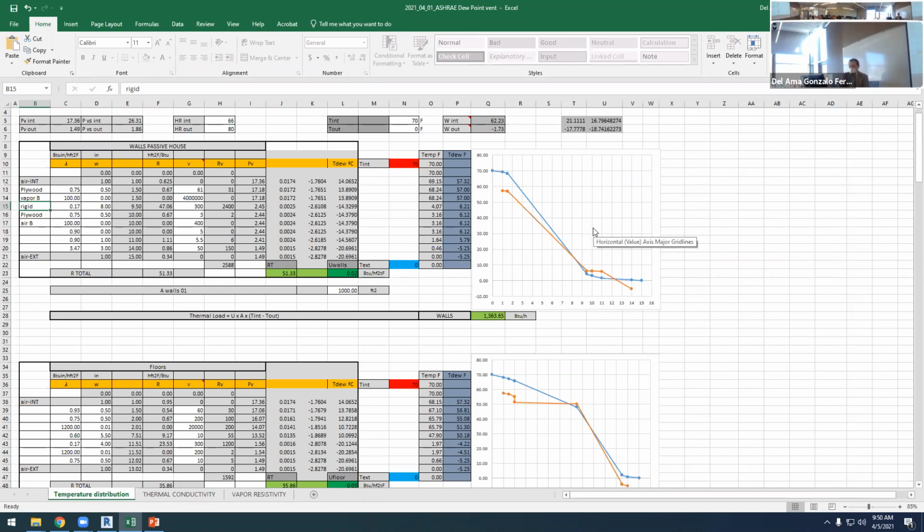But in roofs, using cellulose is quite complicated because they are very exposed to water. That's why using at least a thin layer, 2 or 3 inches of rigid insulation, I think it's better. If we combine 10 inches of cellulose and 2 inches of rigid insulation, from the thermal point of view, it would be perfect, and we will prevent these moisture issues.